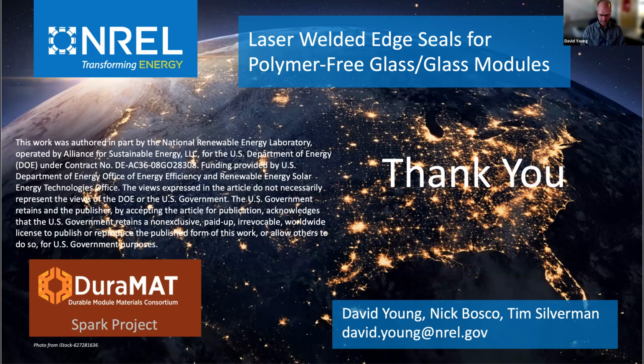Okay. Have you looked at the ease of the glass separation? Yeah. Okay, so I'll take the first question. So holding the cells in place, what I envisioned was essentially what the NICE module is doing, and also what is happening up at CSU and with that, I forget the name of that company up there. But essentially, you rely on the ribbons that are soldered between the cells to essentially hold everything in place. The whole thing is just one big web and held together by the ribbons, and then they're tacked down wherever they exit the module. So that is not a big deal.